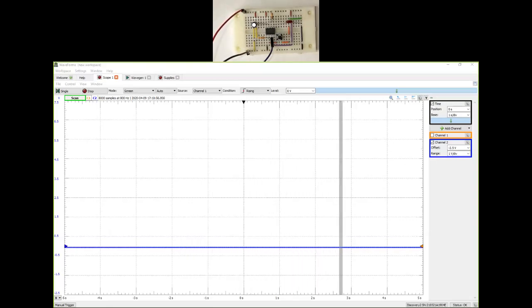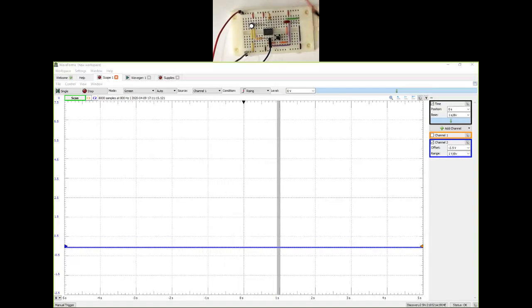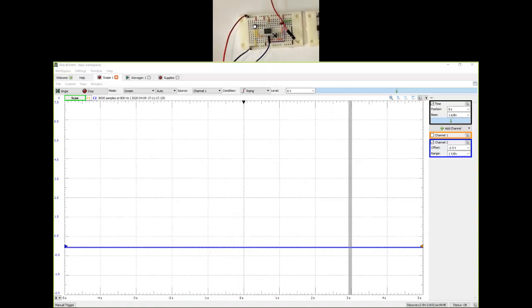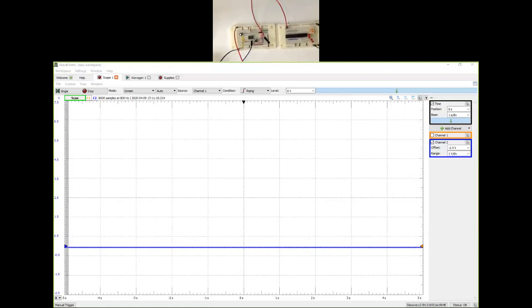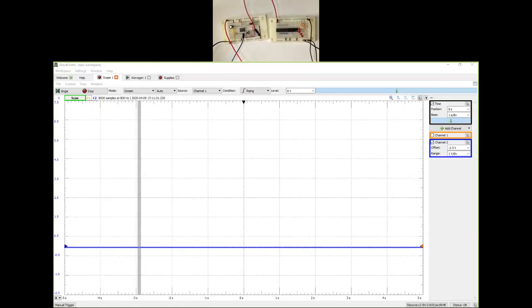So that's a quick test of the real switch along with the pull-up resistor incorporated into your circuit. The last thing, and actually the true test of our circuit, is going to be to be able to trigger a 4-bit counter that was designed and built in experiment 7 part D.